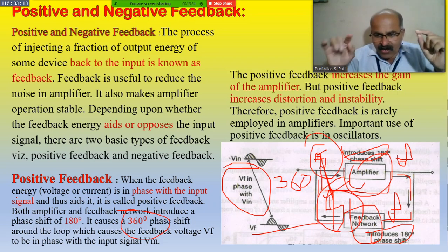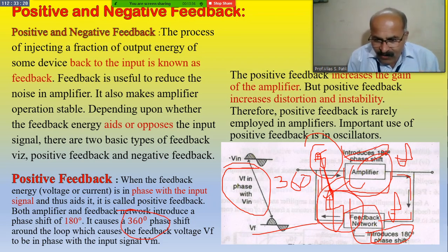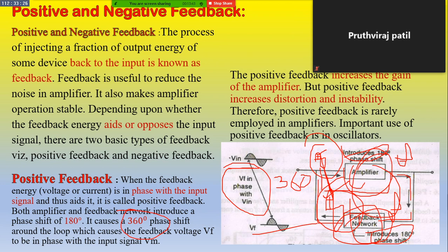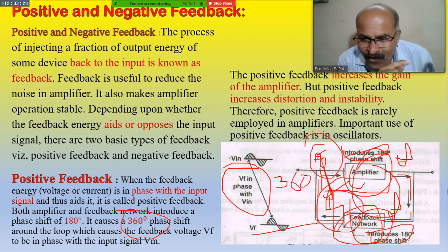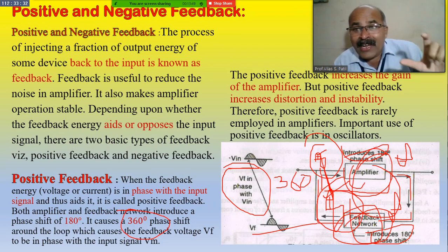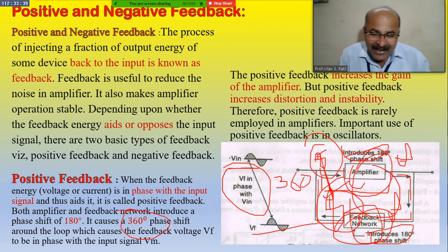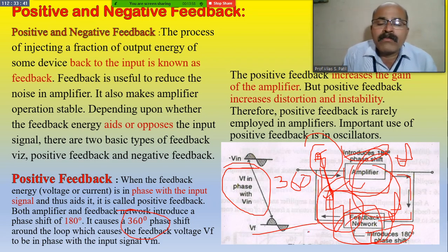This 180 degree and this 180 degree phase shift are aligned, and the total phase shift of 360 degree is introduced. At this time the original input is V in, and feedback input is VF.